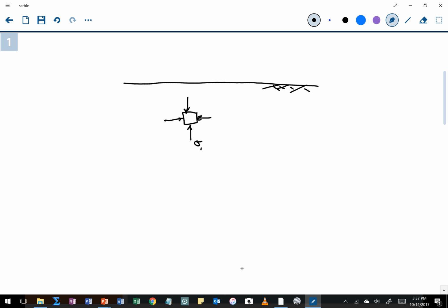And those stresses we typically say are the geostatic stresses, or the stresses from the weight of all this overburden soil that is on top of our soil element. We may even have some shear stresses if we have an embankment up here, and that embankment is applying some sort of shear demand on our soil. And so if that's the case, we may have shear.